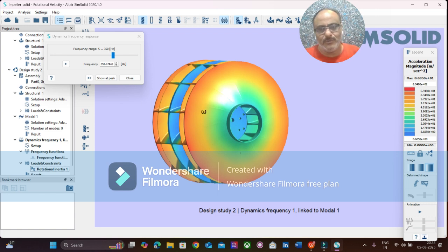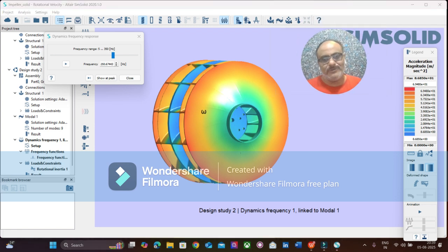Each screw is going to experience this: let's say the aircraft is trying to take off and the g force is increasing. Now it has become 2.5 g, or about 5 g at a certain time, and then 12 g at some point. So there is a dynamic variation of g force, and all of it is going to act on the screws. Every screw is connected to the electronic modules within the cockpit, and those screws are supposed to sustain these g forces or shock loads.